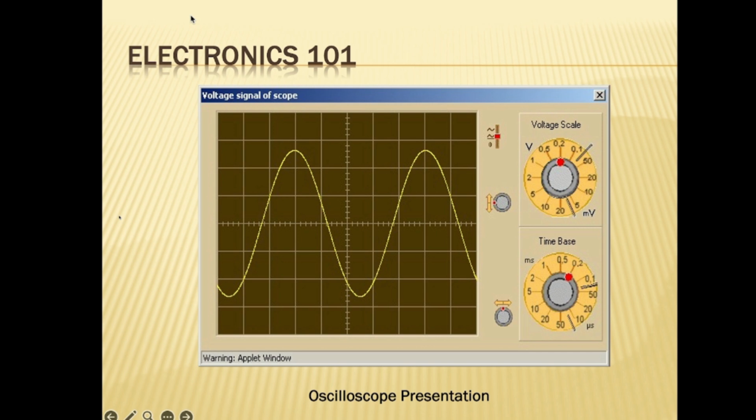On that particular one, I set it at 0.2 of a volt, so it's 0.2 of a volt from there to there. So if I want to know the value from there all the way down to here, I'd have to add up all those little squares and come up with a voltage value for that waveform. Likewise, the frequency going across is called the time base, or the time oscillator, and we would set that for whatever time we need to make a good display, get a good solid signal on it. So between those two, we juggle it and we get it where it looks right.